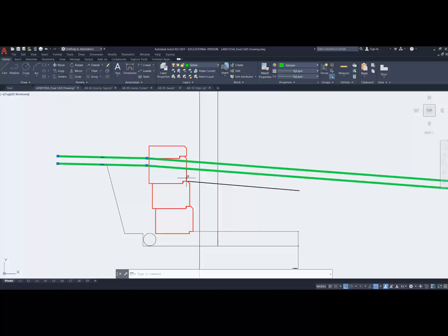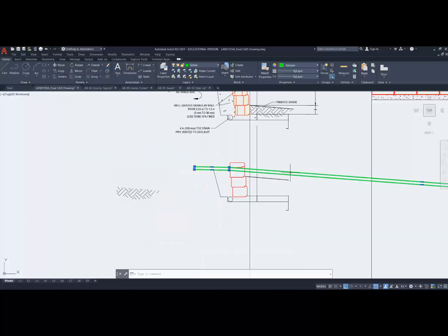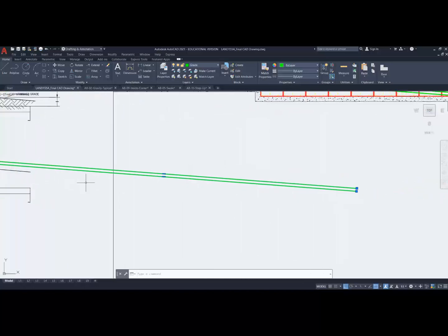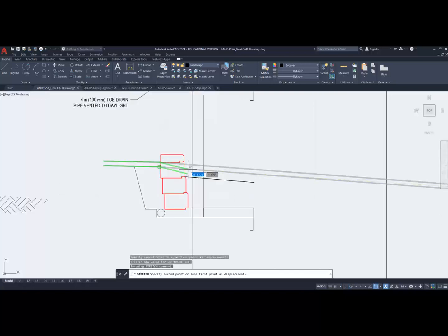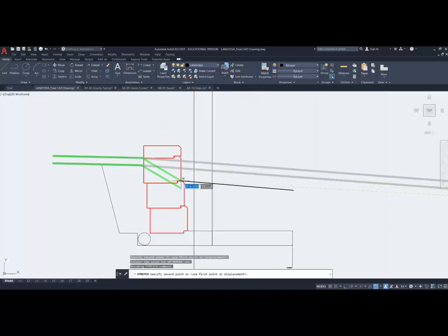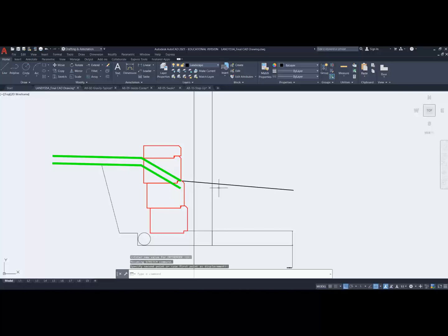That's where it enters, and this is where it's going to come out much lower. So let's use this line work here. So let's stretch this from there. And it's going to come out here. So that's where grade is actually shown from the end view. Everything below this will be hidden lines. Everything above it will be solid lines.